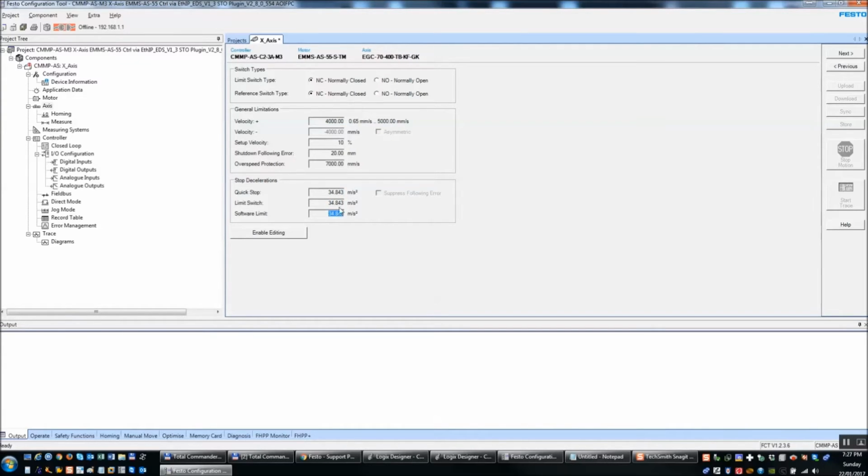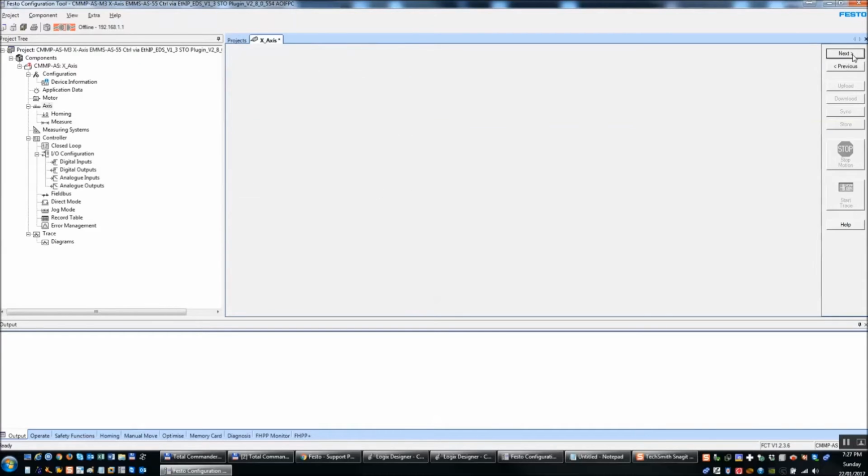The items down here are extremely important, because when you drop the enable, for example, or you have a fault, it'll use these decelerations to stop the axis. So, for the sake of argument here, 555. Don't want to stop the axis too abruptly, could possibly damage some mechanics. And I'm going to put the max in for speed, and then we've got our things. Hopefully you're using normally closed, because that's fail-safe, if you know what that is, I hope.